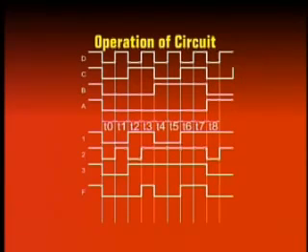The operation of the circuit, which is based on the product of sums simplified expression, also proves that the product of sums based expression determined from the truth table and the Karnaugh map results in a circuit which operates in an identical manner to that of a sum of products based circuit.